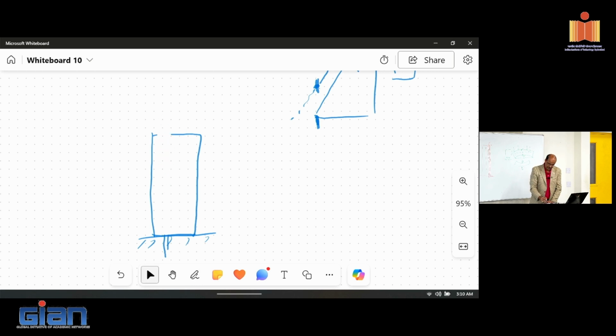Well, there are different ways to establish a jointed connection, but one way is just to use a strand which is unbonded along the entire length, and then establish connections at the top and bottom of the system. So this is anchored into the foundation, anchored at the top. In between it is not bonded to the concrete.